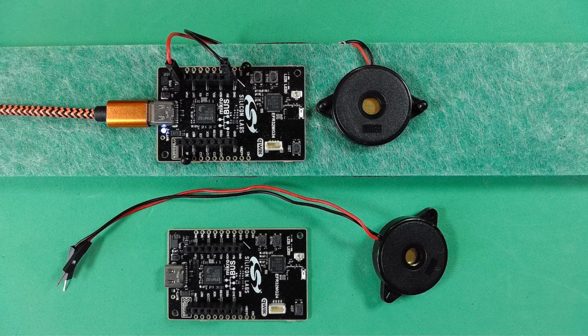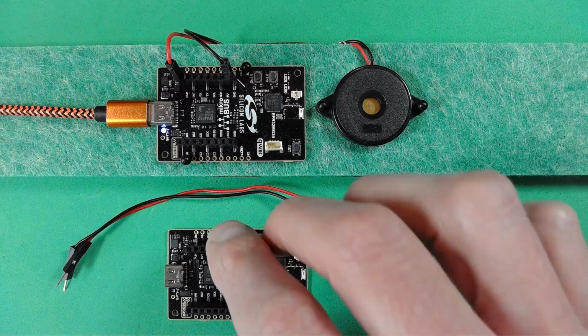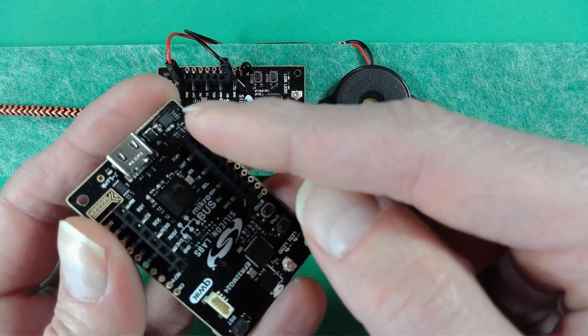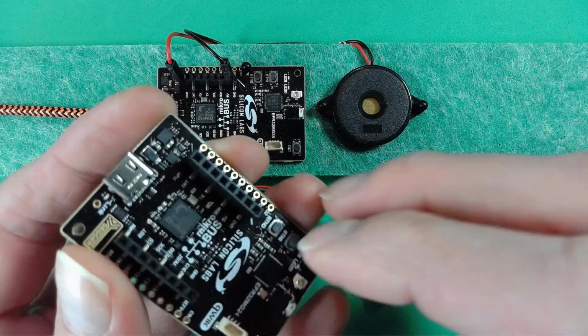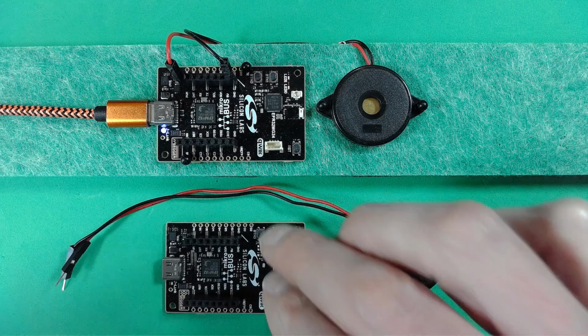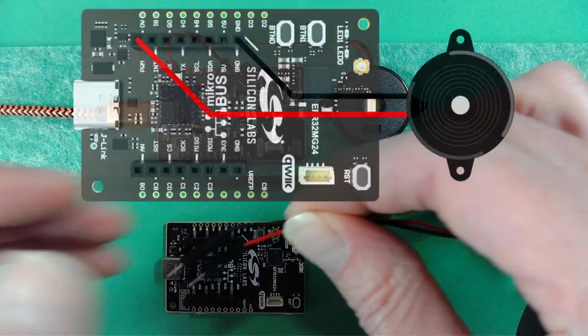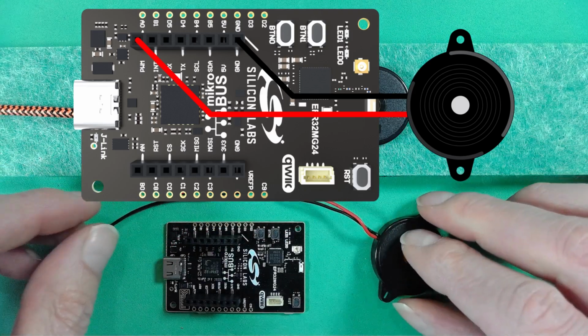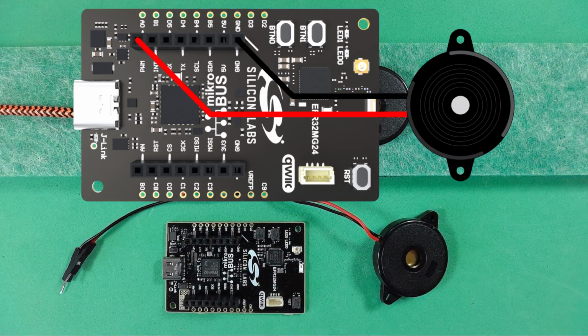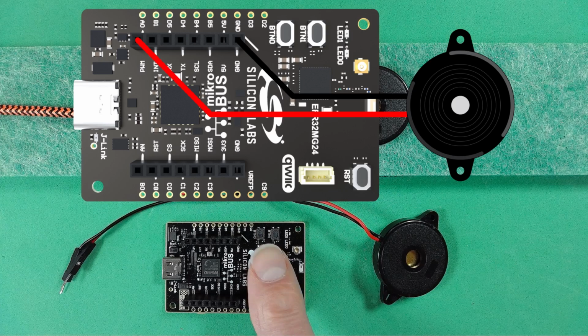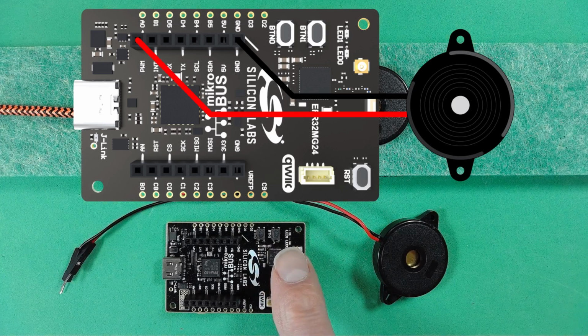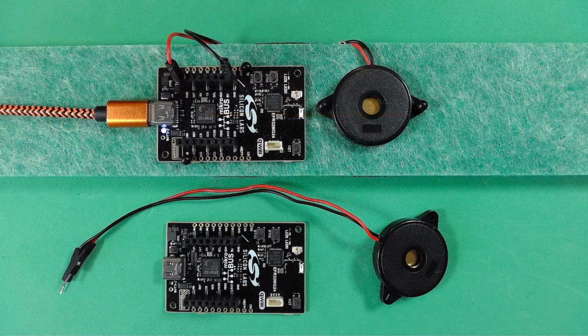The easiest board to work with is the Silicon Labs XG24 Explorer kit. This comes with header sockets fitted to form a microbus connector. By adding pins to the piezo buzzer wires, you can simply connect it to the ground and PWM pins on the header socket. This board also has the 2 buttons and LEDs that are also used by the application. However, this board does not provide an easy method to power it from a battery, which makes it less portable.